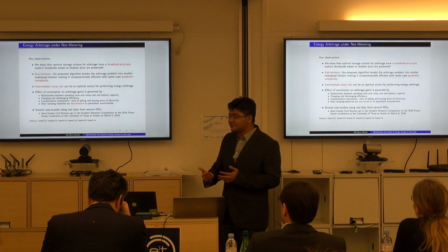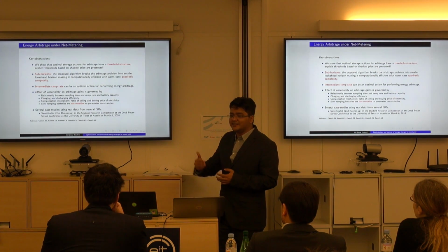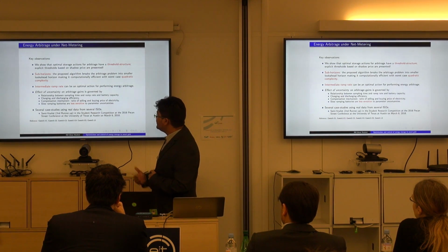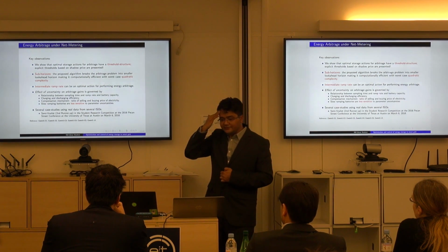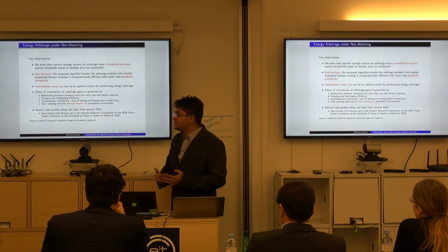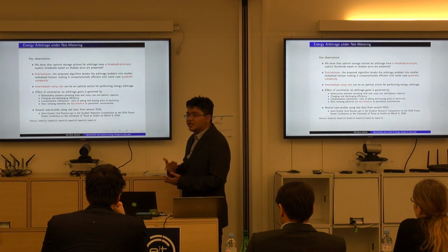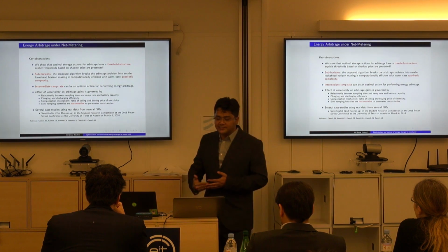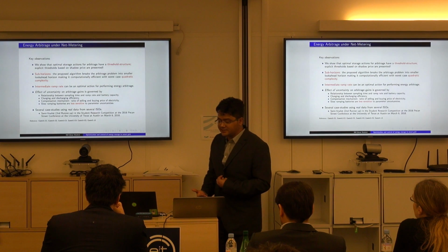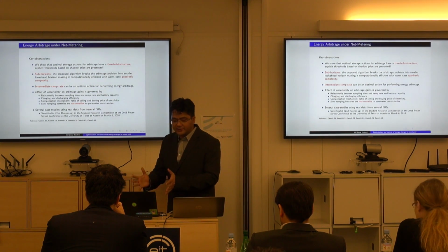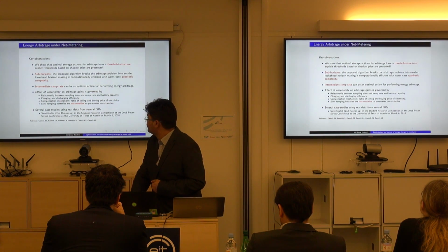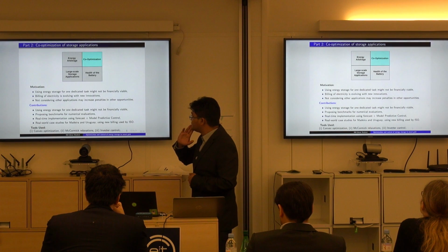There are many earlier works which claim that batteries should be operated at either maximum, minimum, or 0, which clearly is not true. Then we see that the effect of uncertainty on arbitrage is governed by battery parameters, how pricing is done, and what are the charging and discharging efficiencies. So all these claims are being shown using some sort of realistic case studies, of different data from different parts of the world. With this, we move to the second part, which is on co-optimization of batteries.